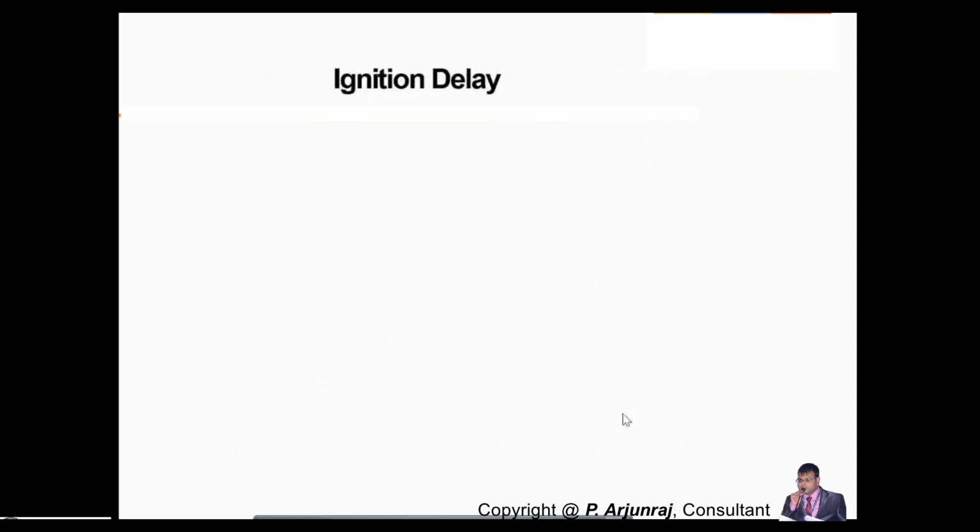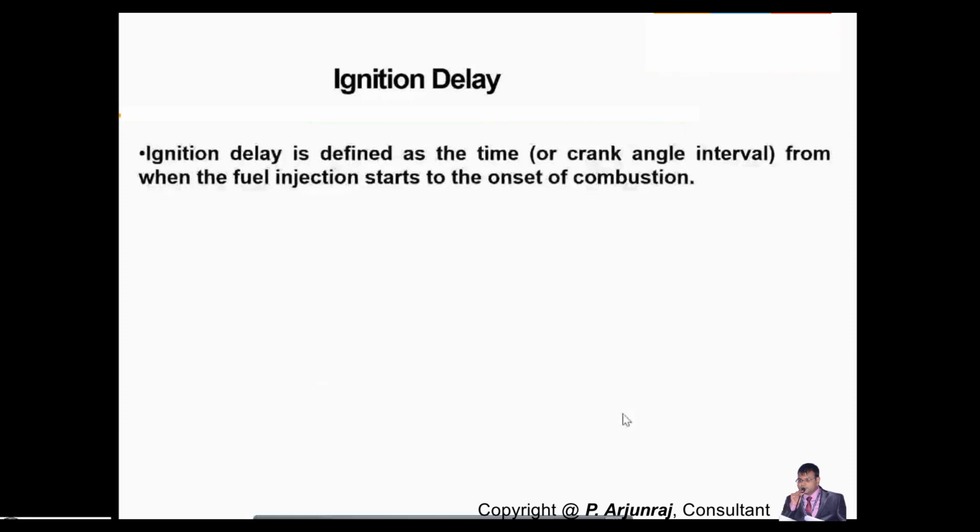So we'll see the ignition delay, which is very much important. How is this ignition delay defined? It is defined as the time or the crank angle interval from when the injection starts to the onset of combustion.